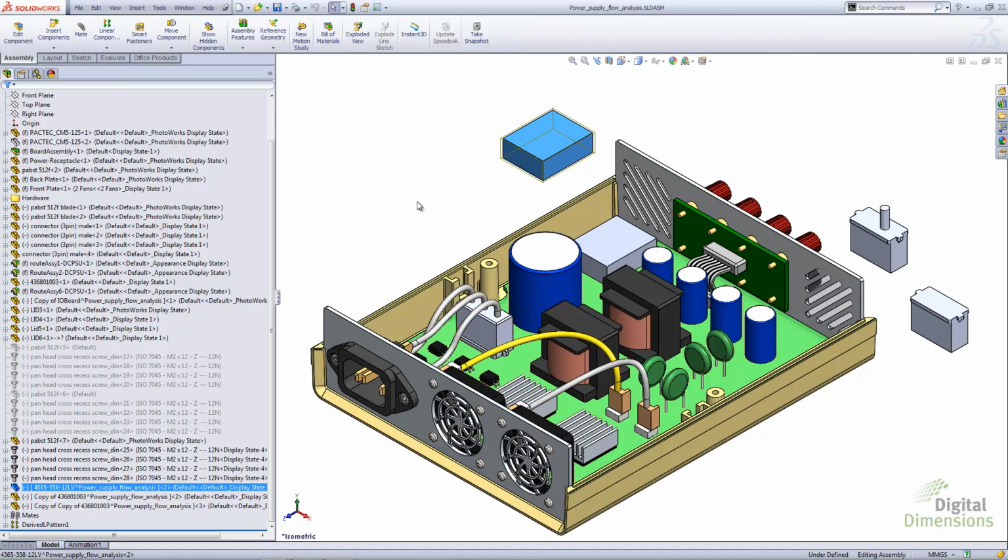The last behavior in this portion of the presentation I want you to be aware of is the fact that we cannot make a drawing file out of virtual components. Drawing files, just by design, require a file reference, and these are only given to external reference parts. So as we know, virtual components only exist within the parent assembly. So what we need to do is save the actual part file externally, so that it does have an external reference. After we've completed that operation, we can go in and generate a regular drawing file to bring in model views, model items, and annotations, etc.